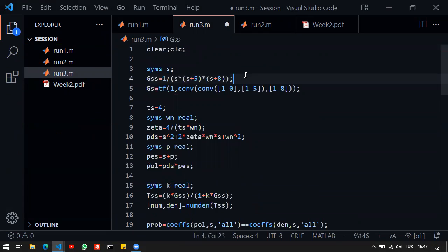Now, at the beginning of today's discussion, we've talked about a first order system, that first order system for any stable P, for example, has zero overshoot. And then we've talked about s squared plus 2 times omega n s plus omega n squared. And if zeta is equal to 1, then that has basically the same poles on the real axis, so they coincide there.